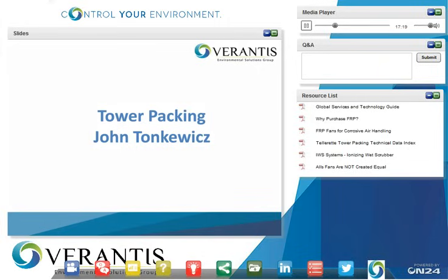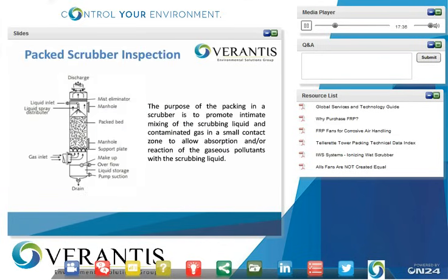Okay, good afternoon, everyone. This is John Tomkowitz. We're going to talk a little bit about packed scrubbers, specifically packing itself, and the first slide, I wanted just to present the basic definition of what the packing is for in the scrubbers. It's designed to promote the intimate mixing of the scrubbing liquid and contaminated gas in a very small contact zone to allow absorption and or reaction of the gaseous pollutants with the scrubbing liquid.